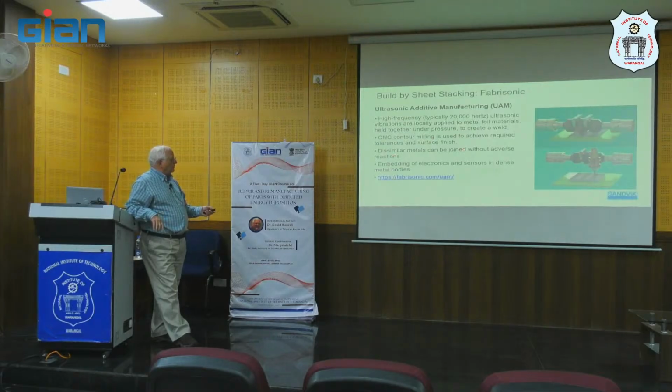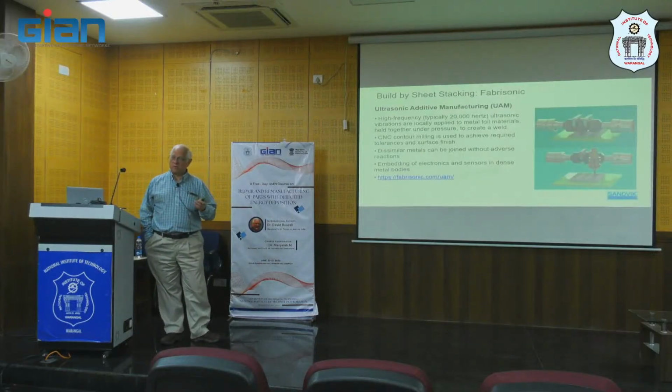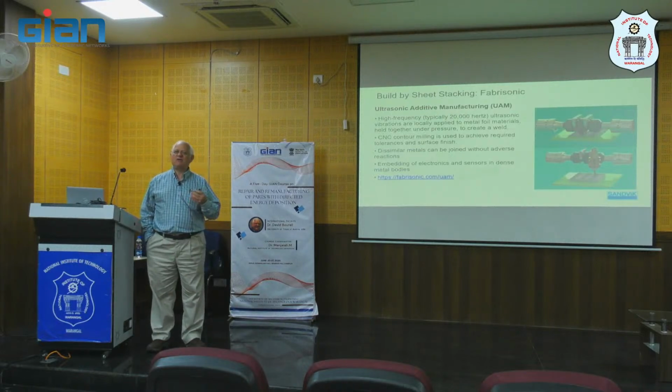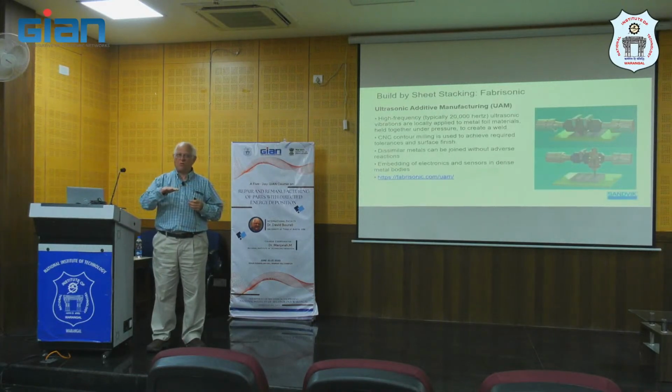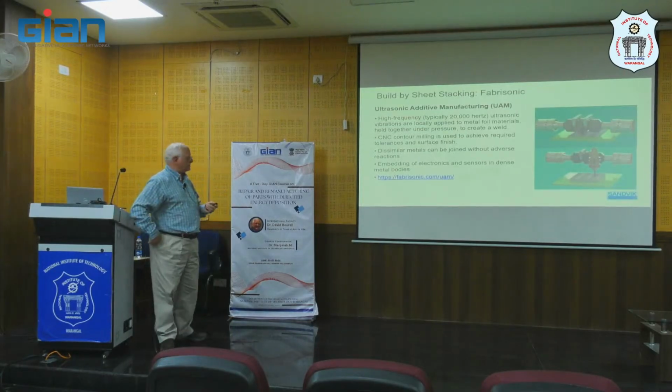You can do dissimilar materials. They typically will join pretty well, except that this is not really a fully functionally graded approach because we're working with foils. So I can do gradation in the Z direction only, and everything else is planar, because of the nature of the foil deposition.